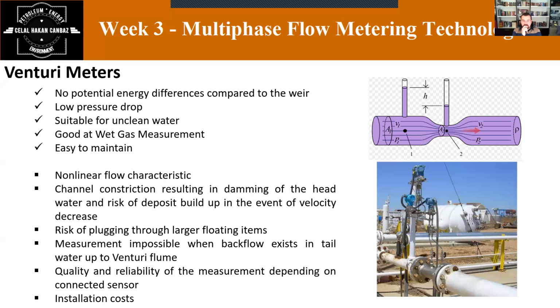You want to continue your flow, but your tanks are full, so it's making a backflow. Because of that, you directly see very big fluctuations in your data, which gives a very high error percentage at that time. You cannot get any production results. Okay. So it's one of the main issues of this venturometer.